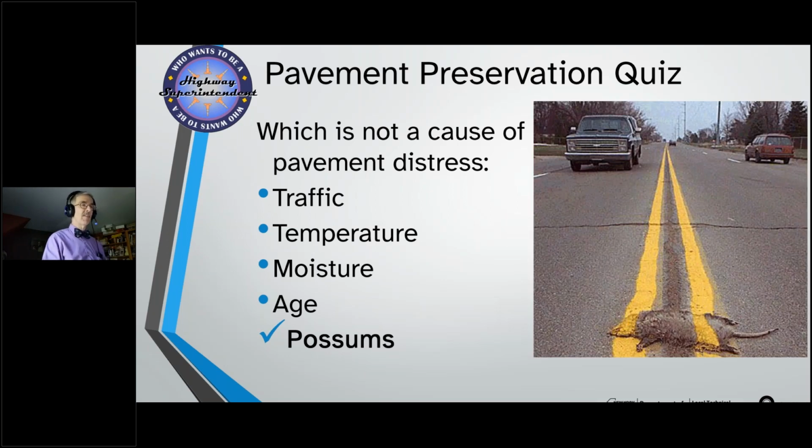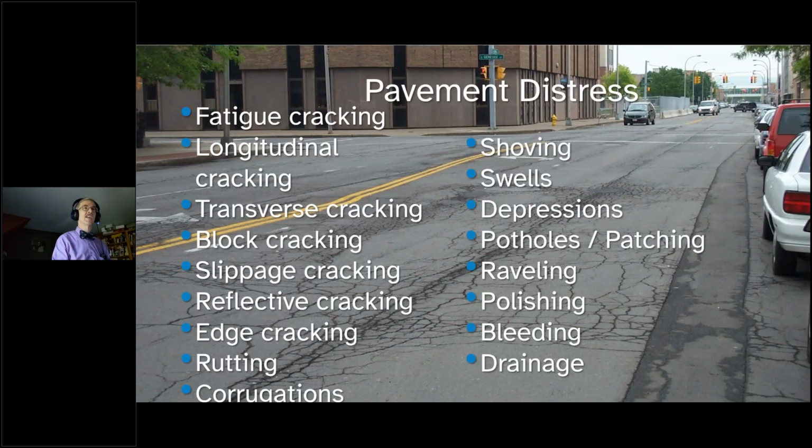So we have the famous photograph from the Arizona DOT of "Not My Problem." Yes, this is a real photograph. We've got several of them ourselves, and they're easy to find. But the thing I want you to remember is there's lots of things to look at. When it comes to pavement distress, there's all kinds of cracking, there's rutting, there's corrugations, potholes, raveling, polishing of the aggregate if you've got an aggregate that's got too much limestone or shale that doesn't even hold up.